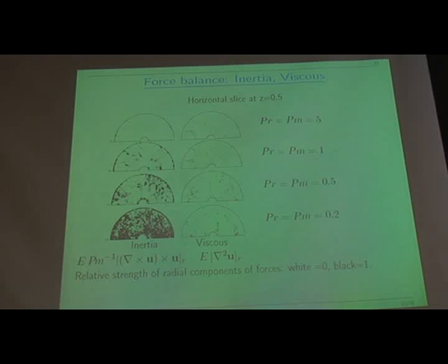You put that back into the nonlinear term, so you get an improved estimate of the nonlinear term at time t using the partially incorrect but approximately correct information at n plus 1, and you compare predictor and corrector. You just look at the modulus of the differences, so if anywhere is wrong, then you cut the time step. Yes.